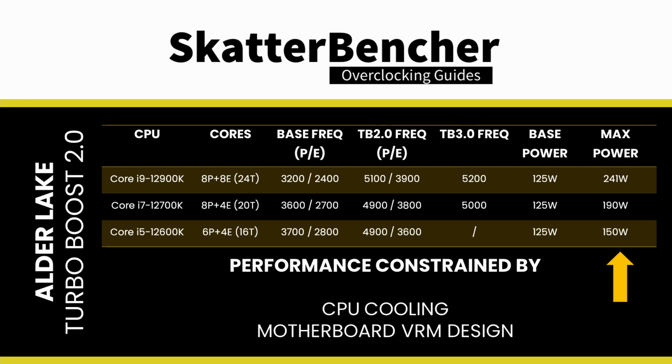If your cooling solution is insufficient, then the processor will reduce the operating frequency at the maximum allowed temperature, or TJ max. For Alder Lake CPUs, that's 100 degrees Celsius. Note that the GIGABYTE Z690 AORUS Master has, by default, Turbo Boost 2.0 power limits unleashed. So, no need to make any BIOS changes to benefit from the additional performance.